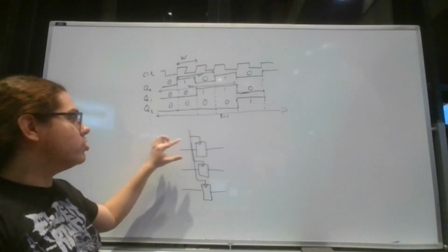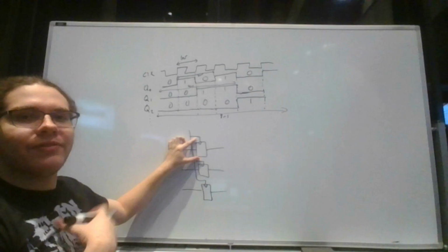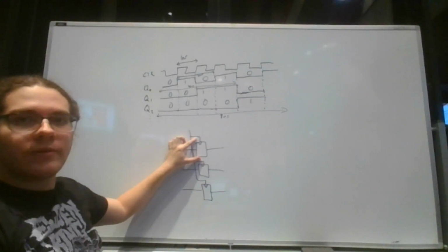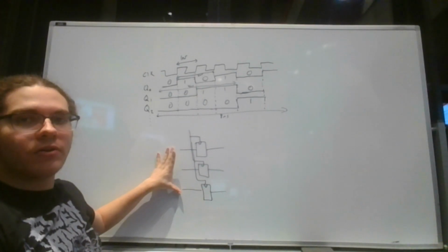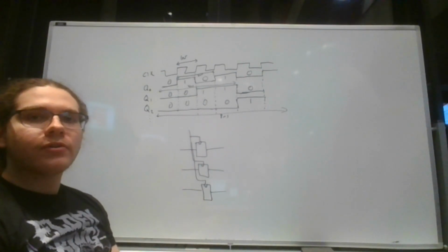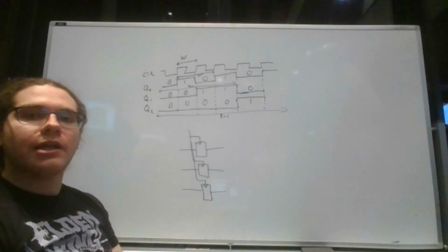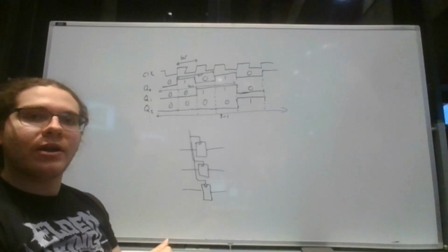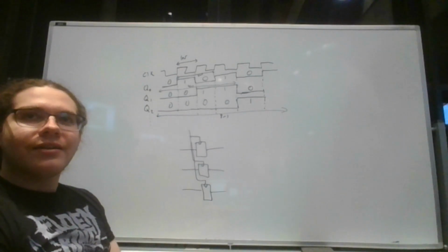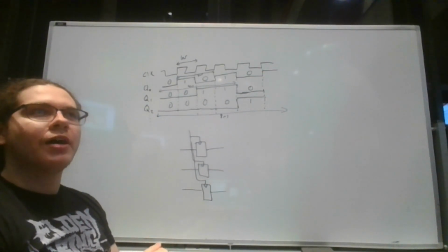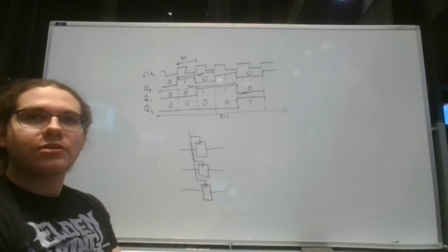If you have just one, you typically call it a flip-flop, and if you have multiple chained together, you refer to the entire congregation as a register. However, you can use them pretty much interchangeably, and if you mention the bit width, people will understand you. If you say a 1-bit register, they know you mean a flip-flop. And if you say a 32-bit flip-flop, you'll probably get weird stares, but they'll know you mean a 32-bit register.